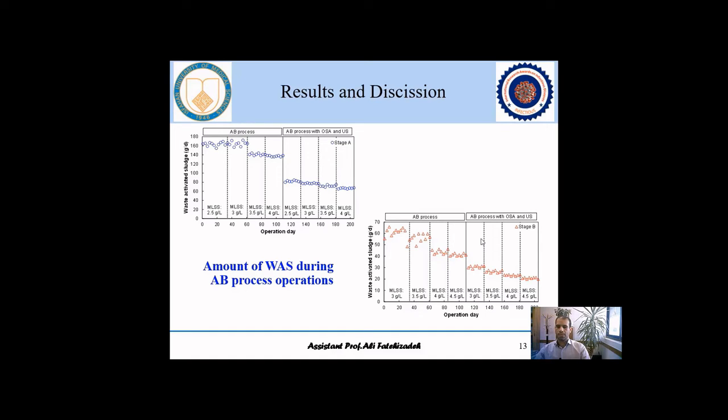The cycling of sludge in oxic and anoxic conditions led to uncoupling metabolism, as the sludge underwent no food and low ORP conditions in the sludge holding time. The minimized substrate residue in the liquid and food storage in the sludge could be related to sludge storage in the holding time, which includes sludge starving under anoxic conditions, and as a result led to reduced excess sludge production.